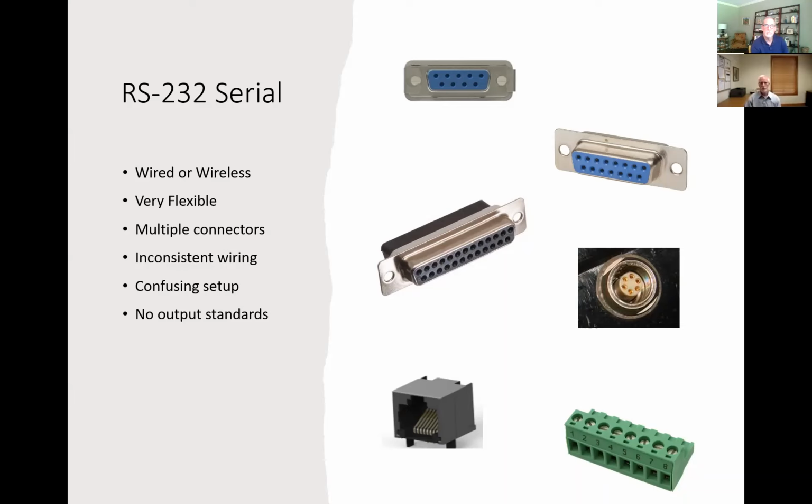You might have 4 different RS232 devices connected to your workstation, all 4 of them at different parameters. All 4 of them might be putting out different data. One might be putting out a measurement only, one might be putting out a date and a time and a measurement and a unit of measurement and the number of tests. So we need to know what's coming out of these devices because there's such an unknown quantity. Once we know that, and we can talk to you about what you need out of that data stream, then we can parse that data to get you exactly what you want.